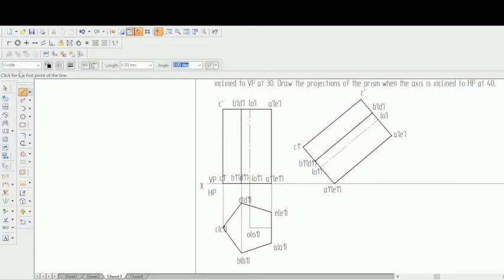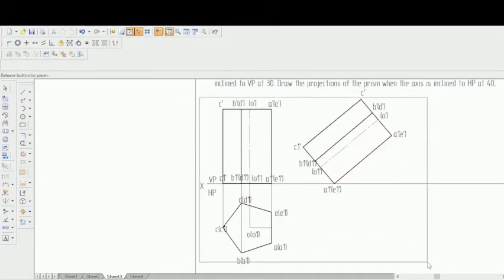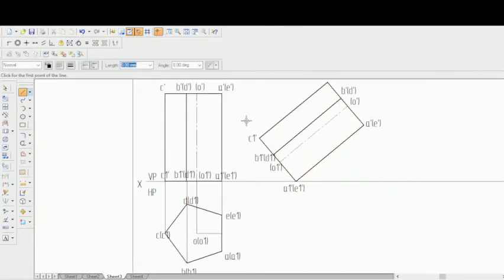Now let's try to draw projections. Let's draw these normal lines. Before drawing, you can even zoom in further if you want, so that as you zoom in you can draw more accurately. Let's draw projections from the top face, A, B, C, A dash, B dash. From A dash to A. So let's try to draw projections.